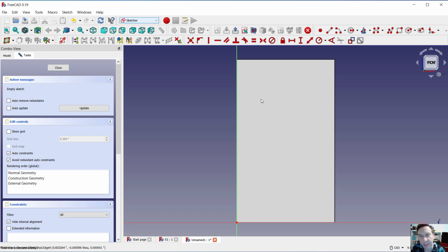Okay, at this point, now that we're here, we're going to go ahead and put in a rectangle. So we're going to go back to the rectangle tool. Before we do that, we have to make some points for it to be able to lock into. So for that, hit this little arrow if you don't see this. And what we're looking for is this tool. Look carefully, it might be hiding somewhere up on the screen. It creates an edge linked to another edge. So select this edge and select this edge right here.